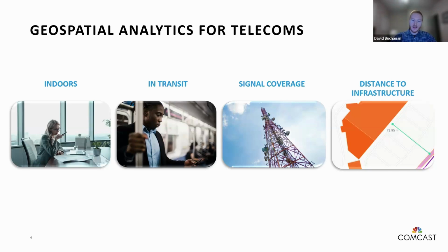Typically you're going to have some type of line string that follows the road you're planning, and then you create a buffer, and then you see how many businesses or homes, using something like the Overture building data set, are within that buffer. And so you get these really great business plans without actually having to send somebody to survey those areas. So you save a ton on cost and on your planning.